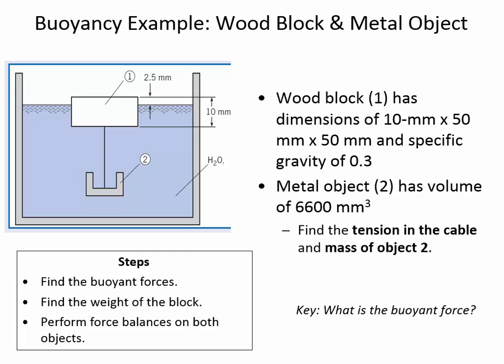And so you're going to say, well, I've got a hydrostatic force at a certain distance. Now you'll know the distance there, and you'll know the magnitude of the force, and that is causing it to turn clockwise, and then the force required to hold that steady is going to be the tension in this cable. So you'll find the tension in the cable by doing the hydrostatic force balance and the moment analysis about the hinge.